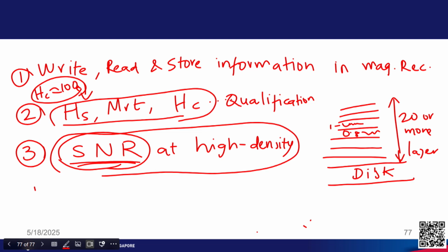Okay. So, these layers are deposited in clean rooms of class 10, I do not know how many of you know. So, class 10 means you take a small volume of space. So, within that space only 10 particles are seen. Okay. In this room, for example, there may be 50,000 particles in that volume.